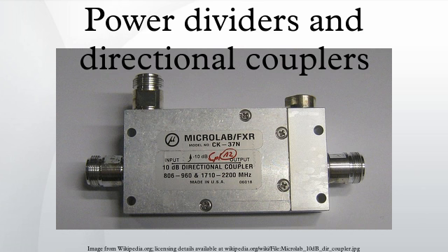Phase difference couplers can be used to create beam tilt in a VHF-FM radio station, by delaying the phase to the lower elements of an antenna array. More generally, phase difference couplers, together with fixed phase delays and antenna arrays, are used in beam-forming networks such as the Butler matrix, to create a radio beam in any prescribed direction.